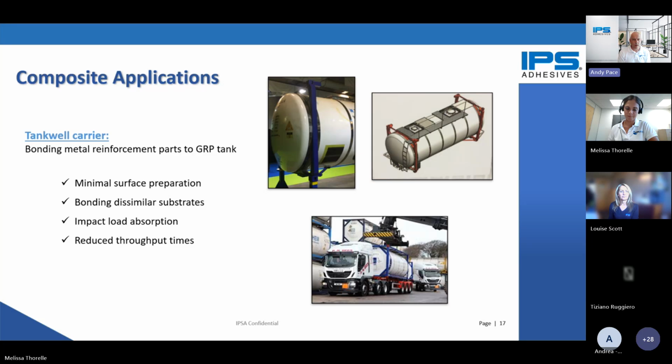Okay. Another great application is composite tank bonding. This is a great market for us. We got into this many years ago. This was brought to our attention when they were trying to take the weight out of the tanks. They did a destruction test on a composite tank that was bonded together with our adhesive, and what we found was that the adhesive and the composite tank absorbed the crash and absorbed the shocks of destruction much better than the metal tanks. And so as a result of the testing, this has now become standard practice for bonding composite tanks.